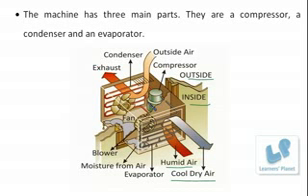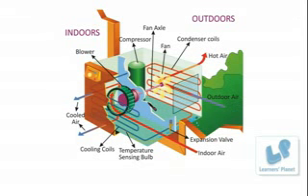Now as the liquid changes to a gas and it evaporates, it extracts heat from the air around it, and the heat in the air is needed to separate the molecules of the fluid from a liquid to a gas. So basically here the evaporator also has metal fins to help exchange the thermal energy with the surrounding air. Now my dear friends, by the time the working fluid leaves the evaporator, it is a cool, low pressure gas, and it then returns to the compressor to begin its trip all over again.